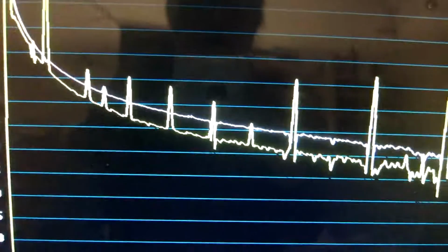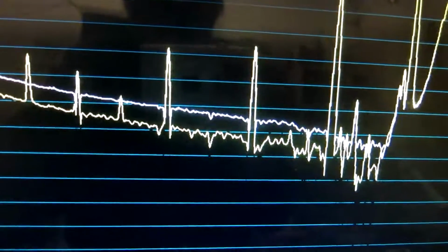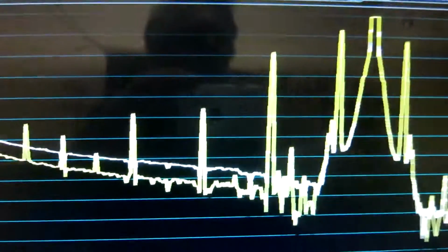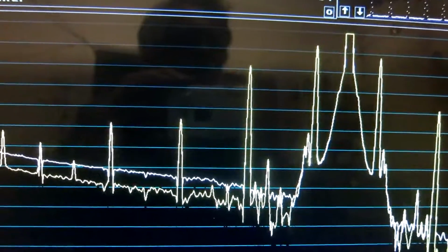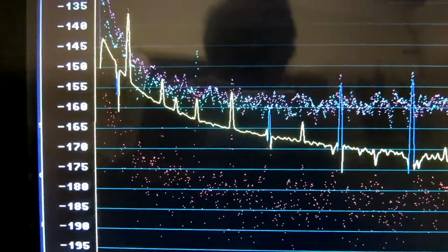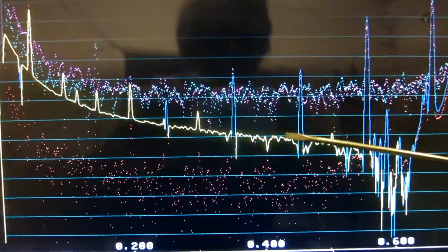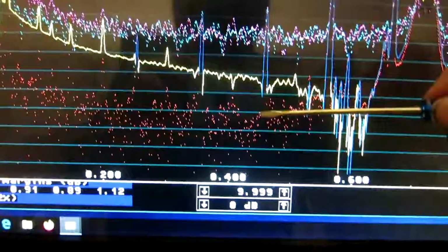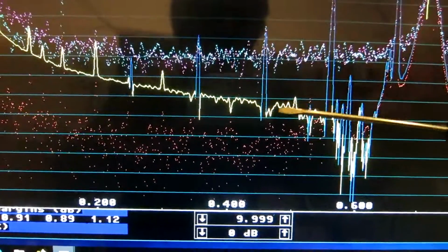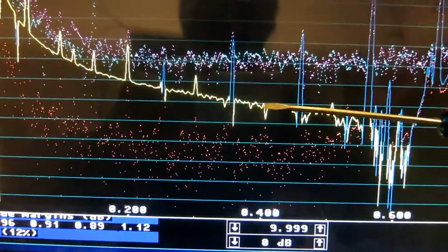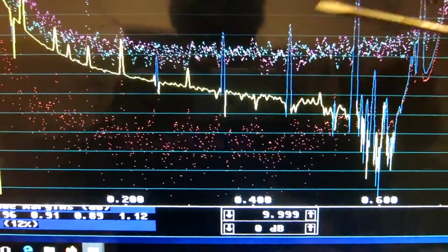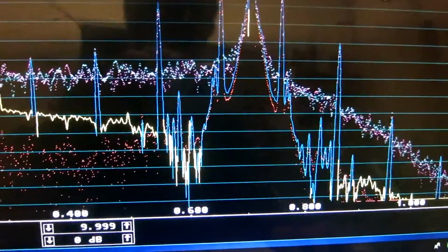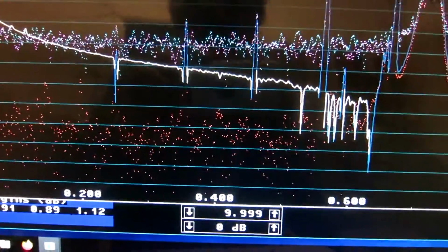I will evaluate the AM and the phase noise from the relevant spectrum. And here is phase noise, and it is clear that up here somewhere the distance from the real part to the imaginary part is getting small. So the curve is a little bit noisy. But I'm not going higher than 400 Hertz, and at 400 Hertz, this is okay. And also 50 Hertz. And I look at the AM noise here, and it is even better.